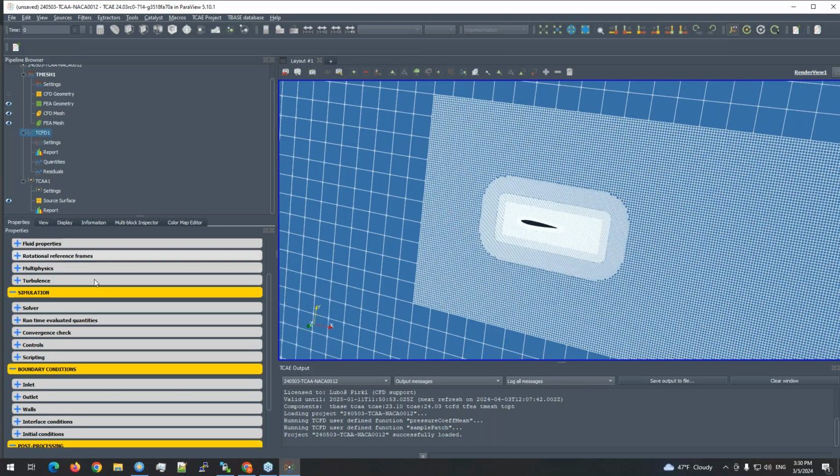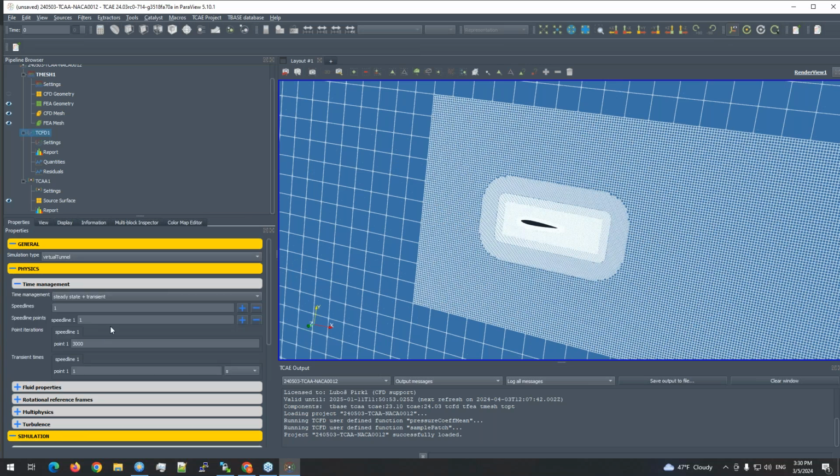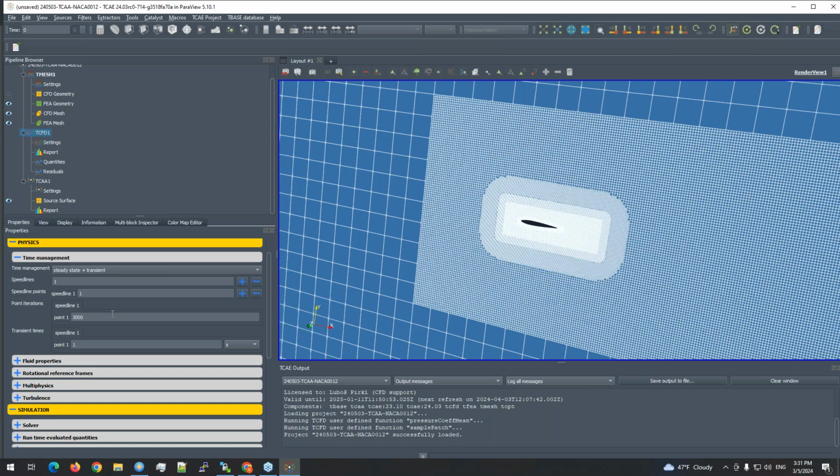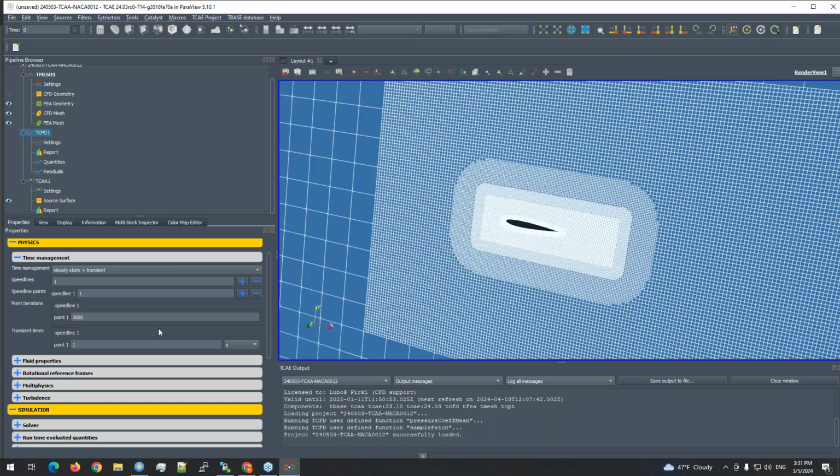When we go back to the GUI, the setup is a standard one. So we tell the times for the simulation. We always suggest to use the steady state initialization, because then the transient converges much faster. It has some initial shape which is close to the real condition near the blade, and then it takes less physical time to evolve to some periodical movement and to some converged flow pattern on the airfoil.